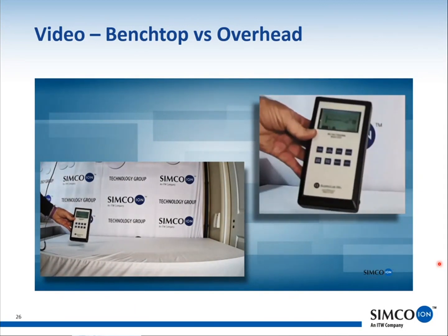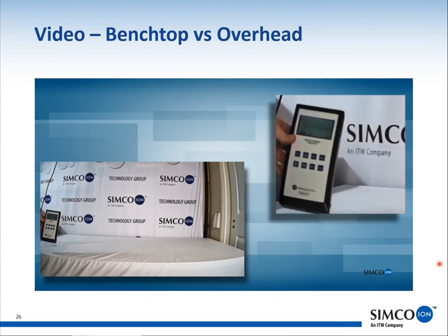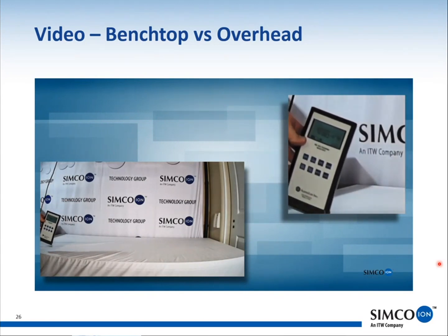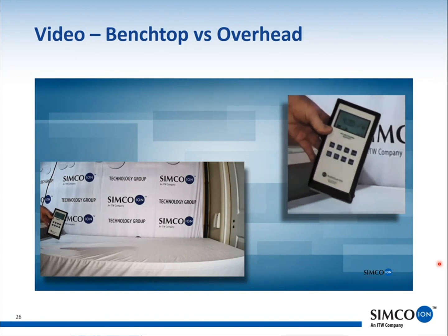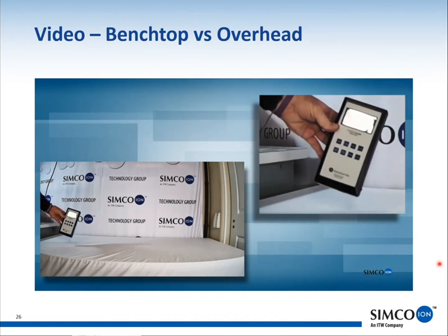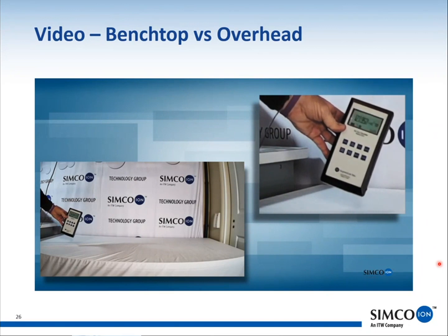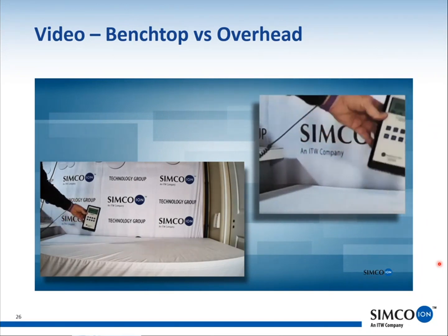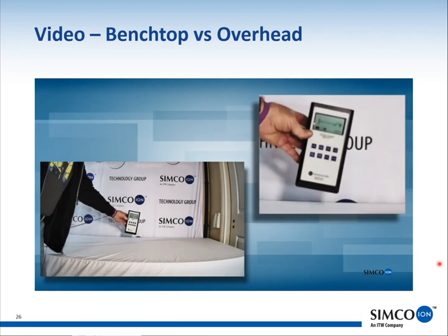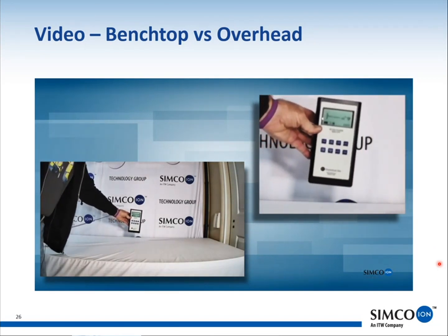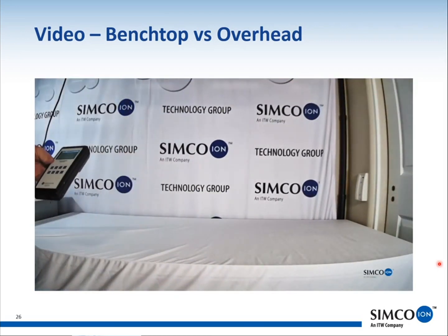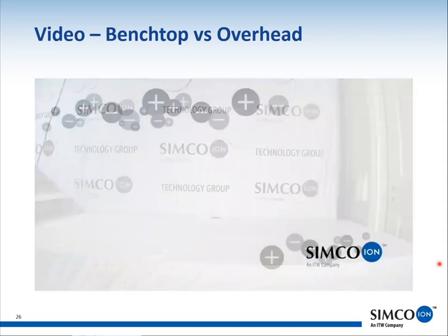The only place we have weak spots, I don't know if you can see this on camera, is when we get over in the corners of the benches. The numbers drop pretty good. But as soon as you move underneath the fan itself, they go much higher. In the back of the bench, again, I get over 200 million ions per cubic centimeter. So if you need to cover an entire workbench, an overhead blower is a much better option for you than a benchtop blower would be.